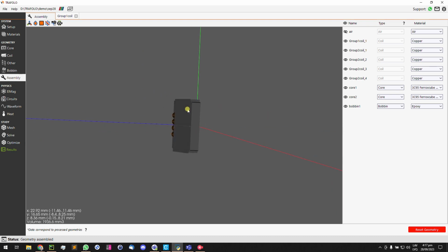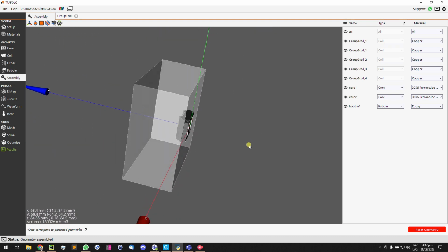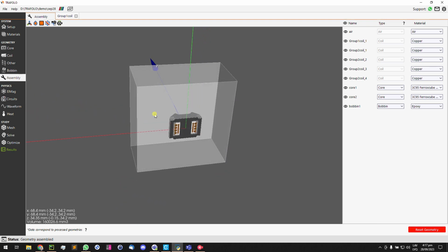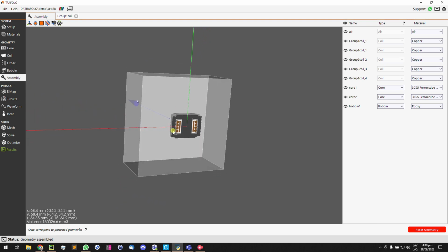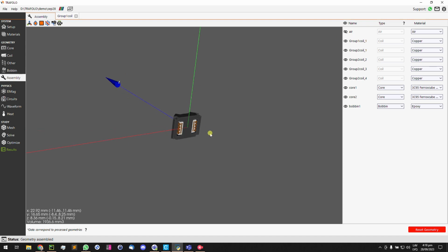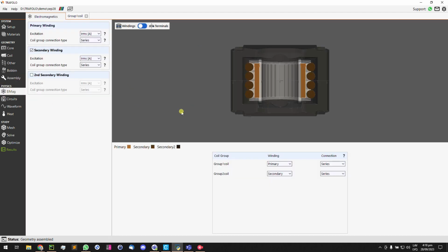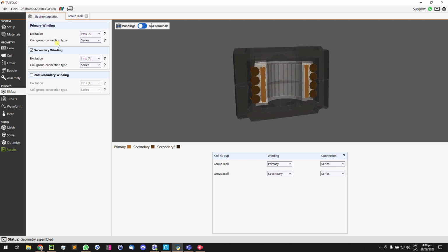This is sampled geometry. This is a symmetrical case. Therefore, you see that the geometry was sliced in half. There's an air domain that was created automatically. For components with core, you don't need a large air domain. For air gapped, for air core inductors, you need very large air domains. But the software will do it for you. Make sure that all types and materials were identified properly.